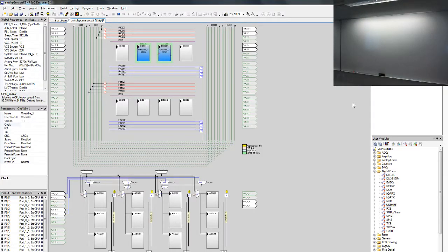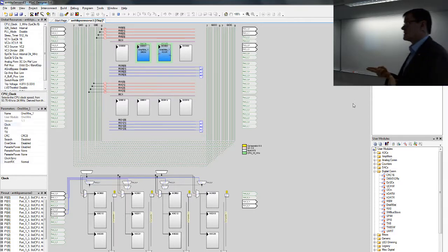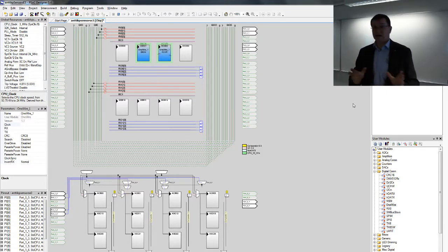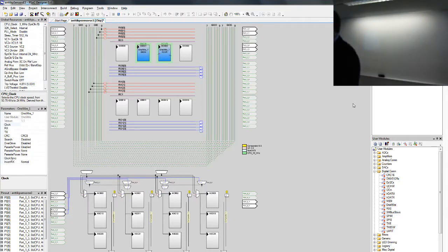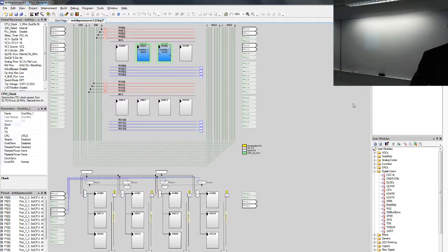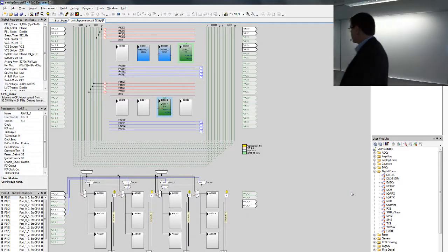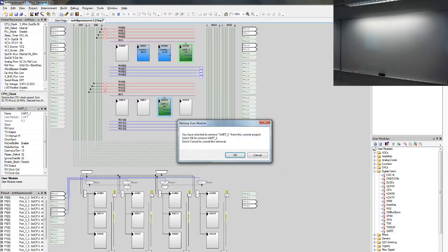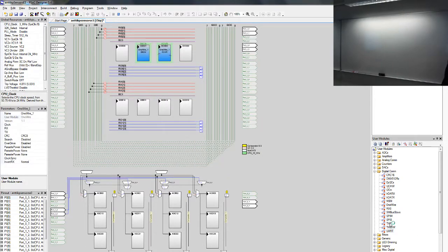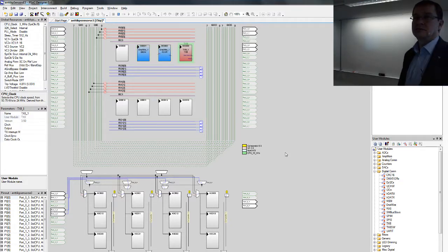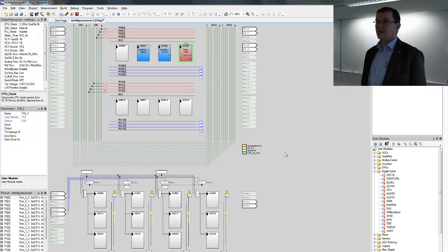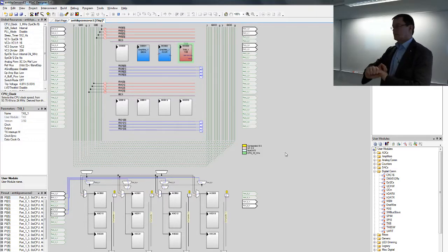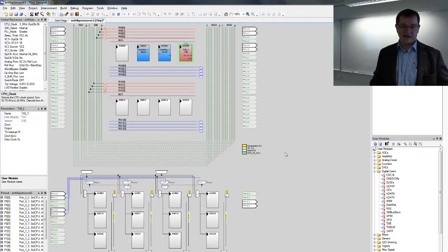Anyways, for that data transmission, for this exercise you would need only a TX8 module, so one directional, you're just sending. But if you want to, you can actually add even this UART device there. I don't care how you make it, but the minimum requirement for this exercise would be to have the transmit data TX8 module there, and configure it so that it has the same parameters as this bridge board.